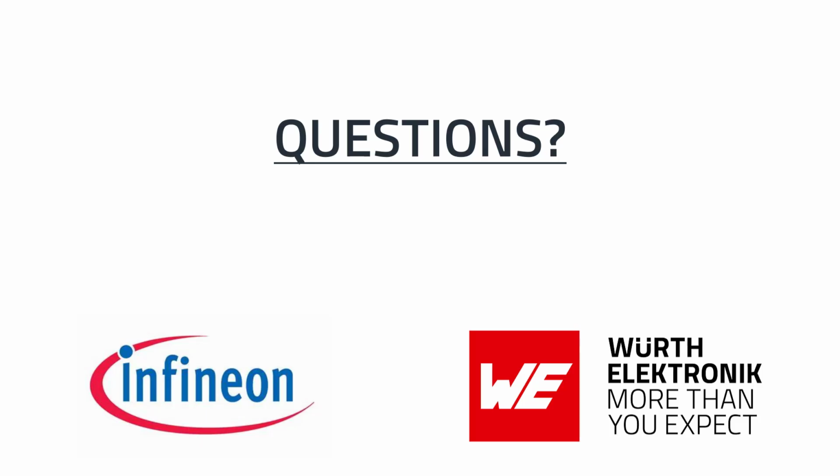Thank you, Jennifer. This next question actually was a common theme for today's webinar: why are there only two frequency and duty cycle settings in the 2EP100R and 2EP101R? Yeah, that's easy. We basically make custom versions of this IC where customers sometimes want to reduce the complexity in assembly. And therefore, we have these two variants where we don't require an external resistor to configure frequency or duty cycle, but we are using a function called pin strapping.